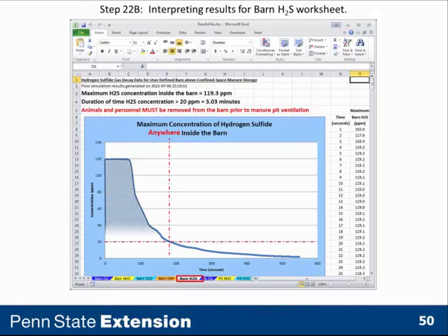Of course, you can select more or less stringent short-term requirements, but what this says is that probably some parts of that barn need to be evacuated. Maybe not all of it, but some parts of it. We have to look at the cut plot animations to determine which portions need to be evacuated prior to a manure pit ventilation event for the initial conditions of this example.